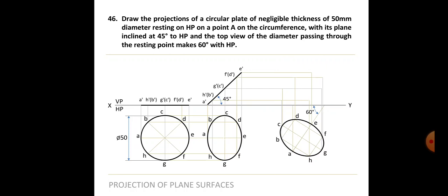Don't simply extend the lines beyond the intersection point. Wherever the corresponding points intersect, please stop there, so that it becomes easy for you to locate the points. For example, you can see the last point here is F on the right hand side, F and F, where it meets, we have exactly stopped it over there. So now you can do the namings, A dash, B dash, C dash, D dash, E dash. It becomes easy for us to mark the corresponding points.